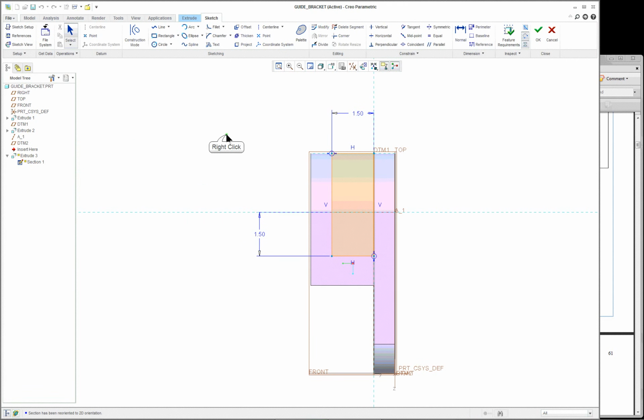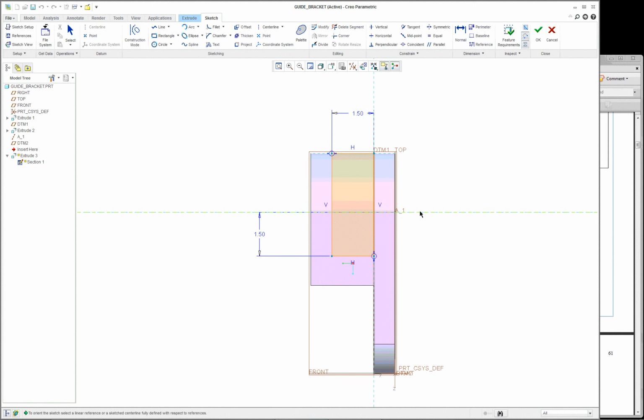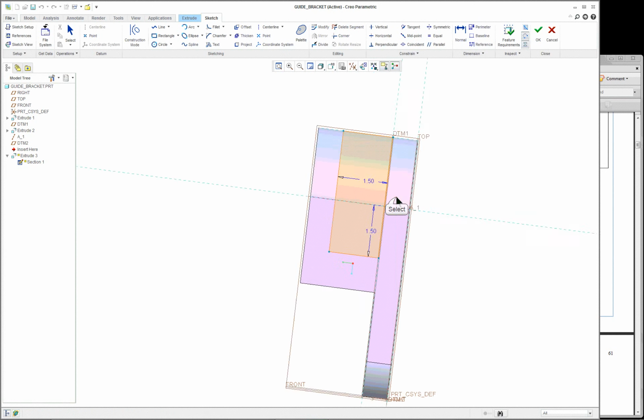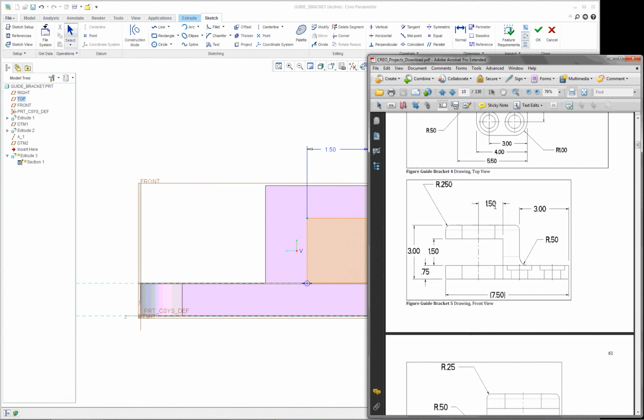The model is turned. It's really no big difference how you turn it. So let's select horizontal reference. Let's pick this one, see what happens. There you go. I'll move my dimensions. So see whether or not your dimensions correspond to what it's asking for in the book. See the 1.5, kind of an odd dimension, but that's what it says, and 1.5 for the distance here.